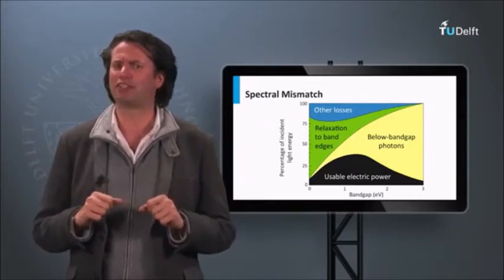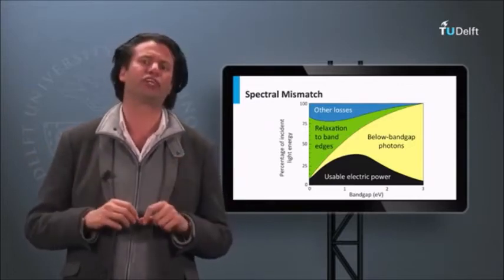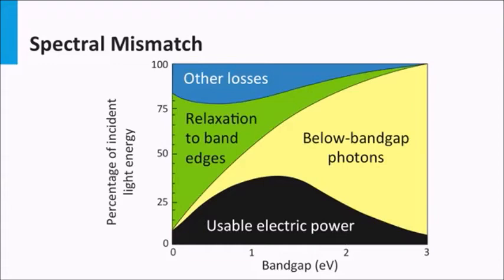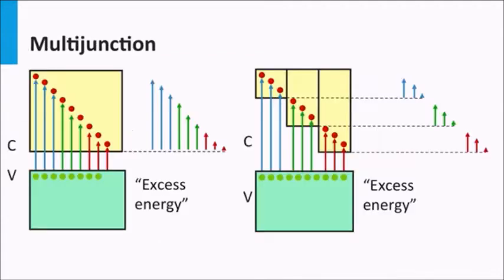Why does the 3-5 technology result in high conversion efficiencies? The 3-5 technology PV devices are based on the multi-junction concept. More than one bandgap material is used. As discussed in week 4, using only one single bandgap material, the theoretical efficiency is limited by the Shockley-Queisser limit. Either a large fraction of the energy of the energetic photons are lost as heat, or the photons below the bandgap are lost as they are not absorbed.